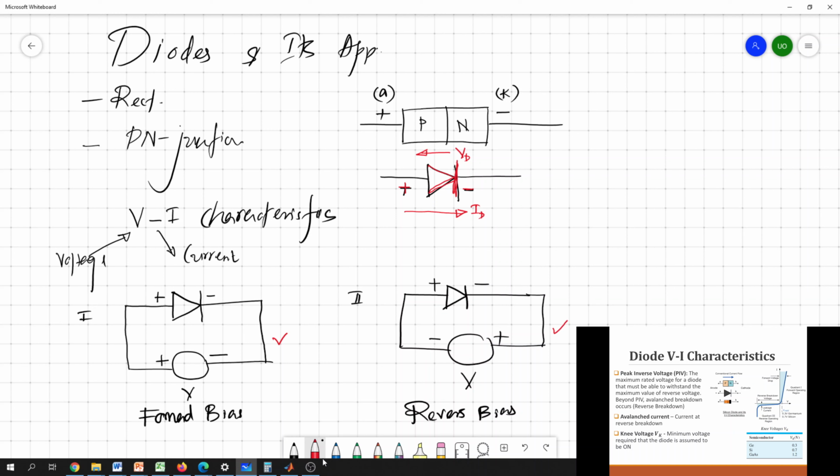Okay, so then you can see the voltage drop across this diode is like this. Here again, this is your VD. What happens in this case? Once you apply Kirchhoff's voltage law, we can simply say that the voltage drop across the diode is exactly equal to the source voltage. There won't be any other voltage drops across the circuit.